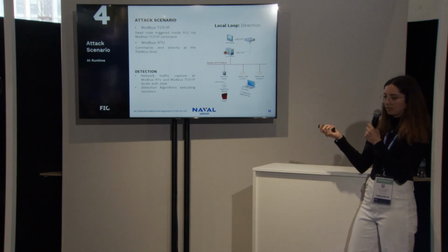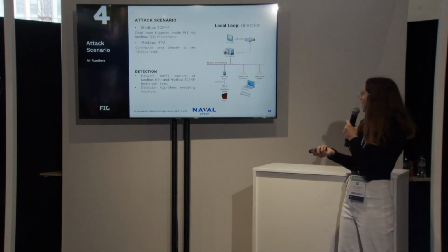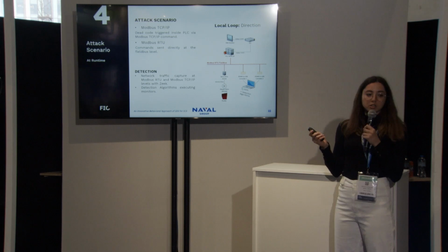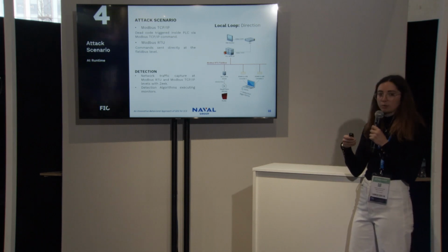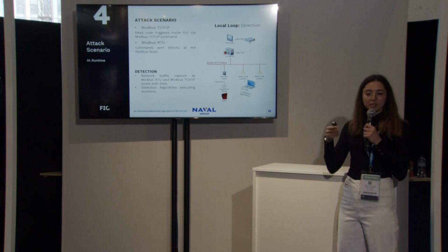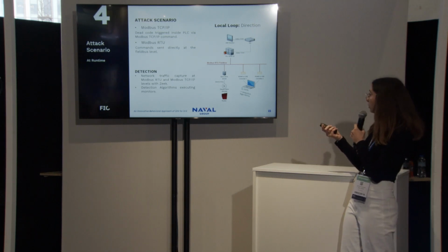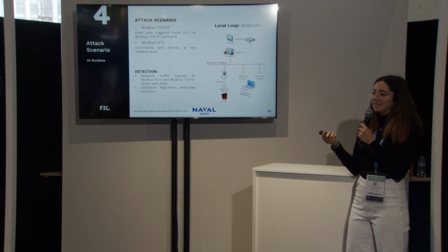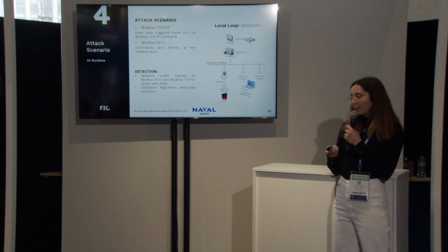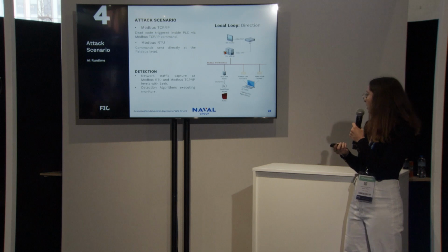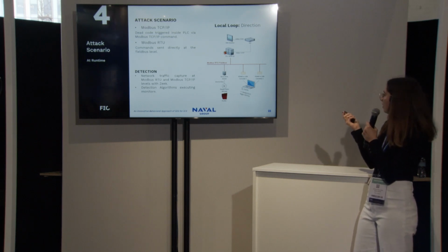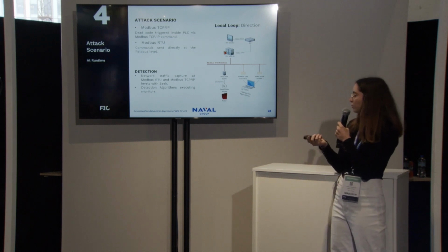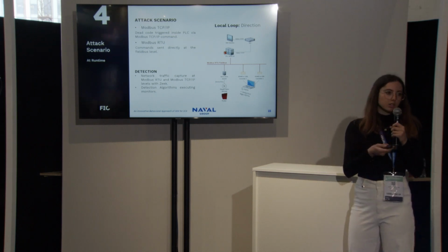I have a slide talking about the attacks later. On the detection side, we also capture traffic at both levels, at field bus level and at Modbus TCP/IP level. We do that using Zeek, the open source IDS. And the detection algorithms, of course, are also executed in order to see if the security properties are violated or not.